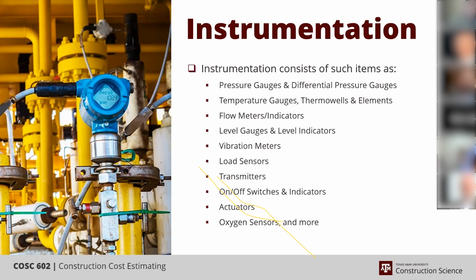But if you go back to what I said about that temperature gauge, if you remove that temperature gauge, you've opened up the system. And so whatever gas or fluids in that system will start coming out of that hole. So the thermal well assists in that process. So that's a very good point. Thanks for bringing that up.